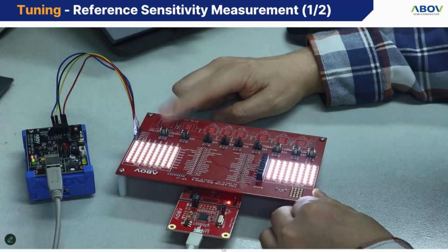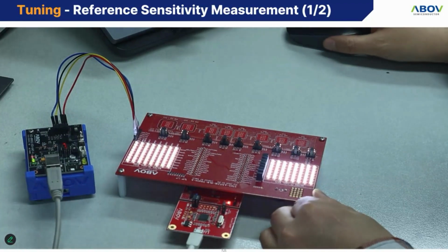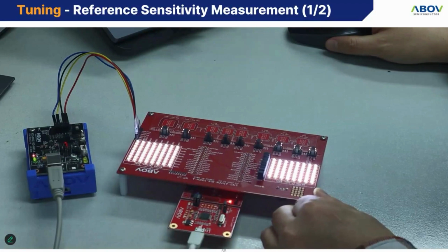Now let's retune for finger touch. First, to check the current finger touch sensitivity, touch the center of the touch pad 5 times consecutively at 1 second intervals. For actual product development, our standard is to test using a metal conductive pole based on the product and touch specifications.